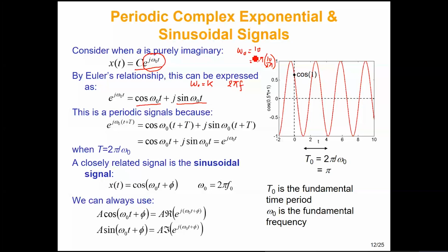Why do we write it this way? Because of this cosine. You remember cosine omega naught t can be written as cosine 2 pi f t. This value which is multiplied by 2 pi is what? This is basically the frequency of that sinusoid in hertz, that is, how many cycles per second we have. That is why instead of just representing omega naught as a number, we represent it as 2 pi multiplied by something, because then just looking at it we exactly know what it actually is.